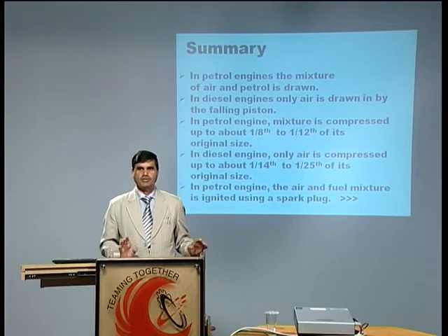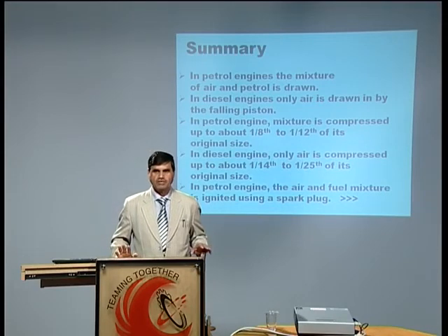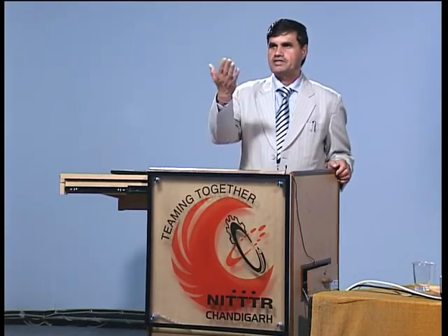So some of the conclusions here: in the case of petrol engine, a homogeneous mixture of air and petrol is applied. In the case of diesel, only air is applied. The compression ratio in the case of petrol engine is ranging from 8 to 12, whereas in the case of diesel engine it is ranging from 14 to 25.